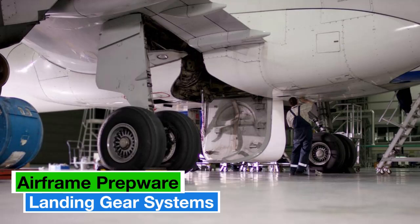A close inspection of a fusible plug reveals the core has experienced some deformation. What is the appropriate maintenance procedure? Replace all the fusible plugs.